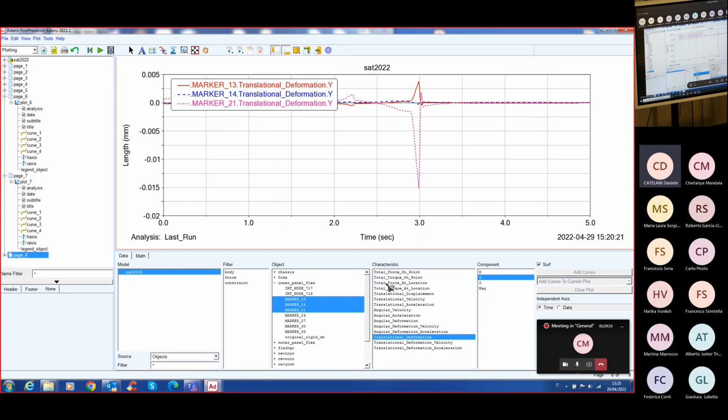You need to run the model for the full simulation, and only at the end of every analysis can you see, okay, this mode is not important, or contributes partially to the total deformation. But if you make a shorter analysis, you don't have the full understanding of the model. Okay. Okay.